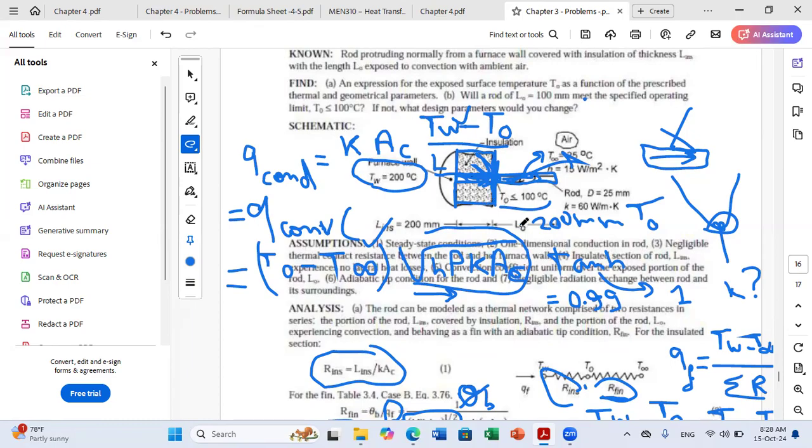So in case you get the value of L for which tanh equals 0.99 larger than 200 millimeters, you say, let me increase the length of my fin that is exposed to the outer environment. If you get it smaller, you say I don't need to add any additional length because it will not help me in evacuating heat. So this is the idea here.